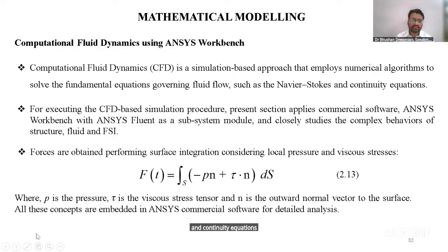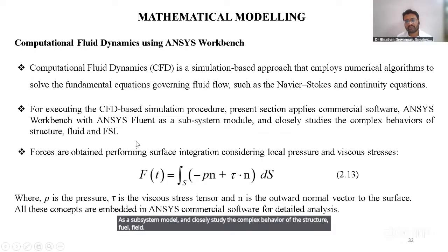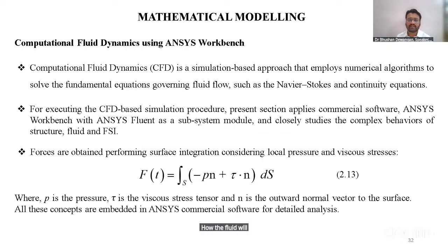For executing such CFD-based simulation, we apply the ANSYS Workbench with Fluent as a subsystem model and closely study the complex behavior of the structure, fluid, and FSI, meaning fluid-structure interaction: how the fluid will interact with the structure when the whole environment has an effect on it.